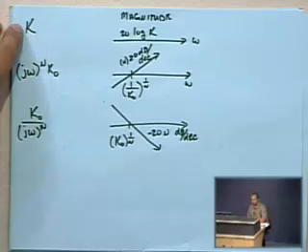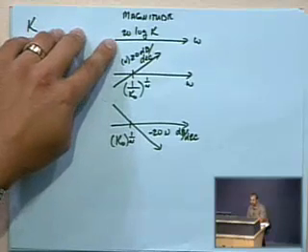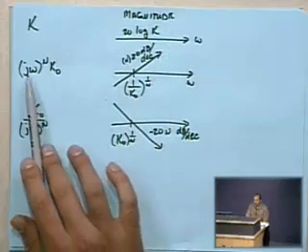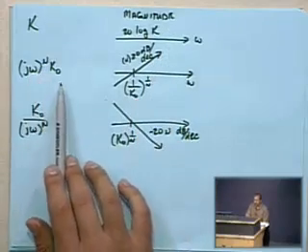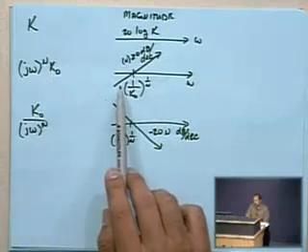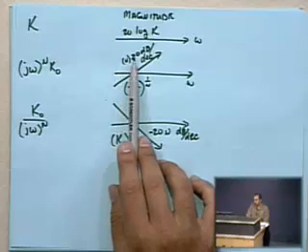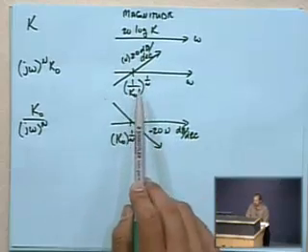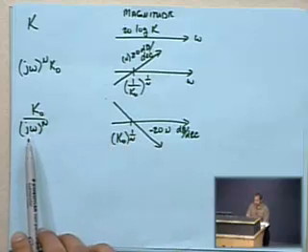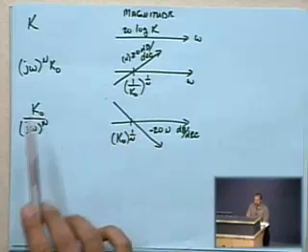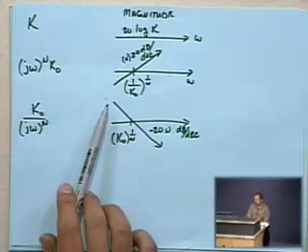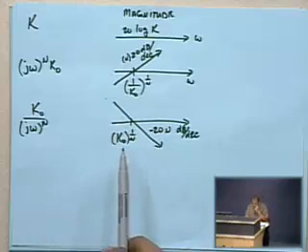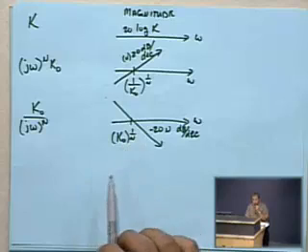Okay, so constant terms k give you a flat line at a magnitude of 20 log k. Zeros at the origin of any degree n, multiplied by the constant k0, will increase at 20 times n decibels per decade, and will cross the origin at a frequency of 1 over k0 to the 1 over nth power. Poles at the origin of the form k0 over j omega to the nth power will decrease at negative 20 times n dB per decade. They will cross the frequency axis at k0 to the 1 over nth power.